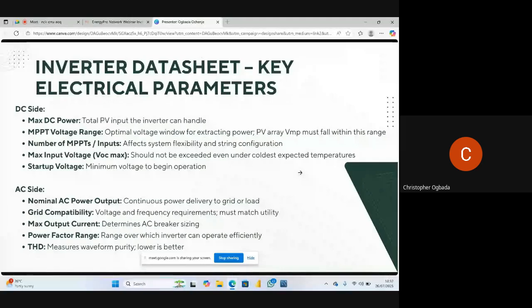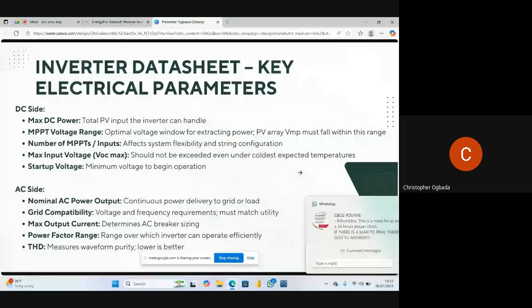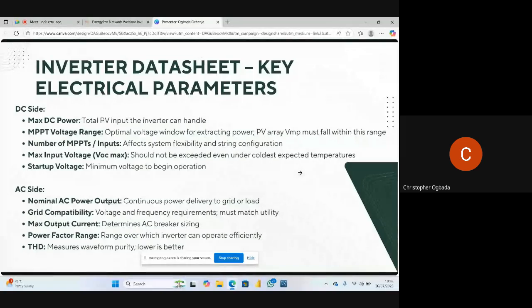I've done an installation for someone who said anytime they are on the inverter, the decoder will not pick. Some appliances are very sensitive to current distortion. When the THDI of your inverter is very high, it means the purity of the sine wave, the waveform of your inverter, is deeper. There's less purity there.